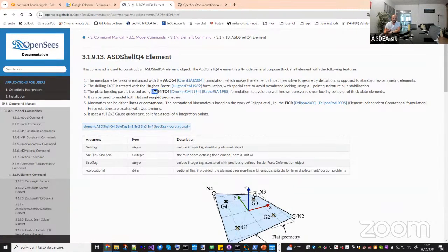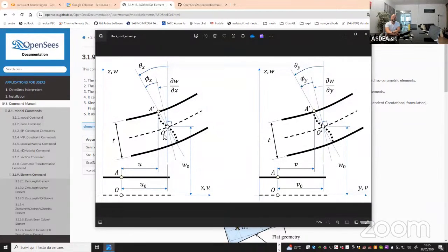So a finite element of a shear deformable shell was not able to give you a good solution in the thin shell limit. Now, if you are interested in the mathematical reason for this, you can go here, but just to give you an idea of why it was happening, you can look at this image. As I said before, what is the shear deformation here? The shear deformation is basically this rotation here, okay? It's taken as the difference between the independent rotation field, which is the entire rotation, minus this rigid rotation, which is the rigid rotation of the normal vector.